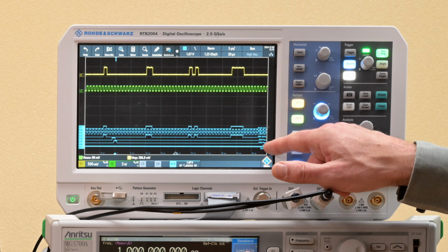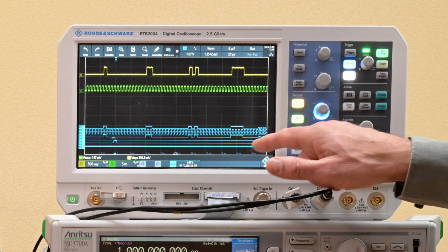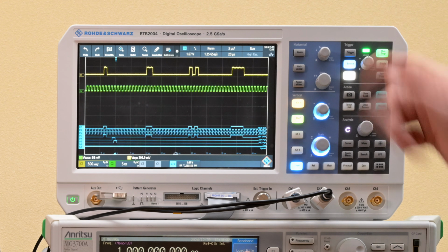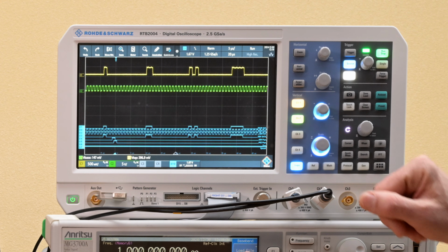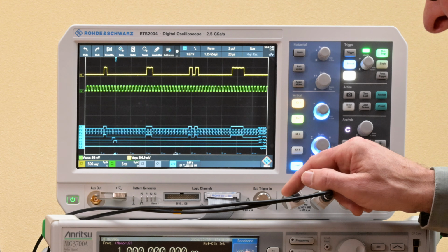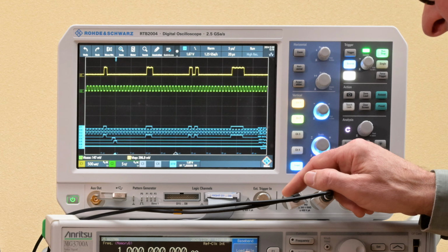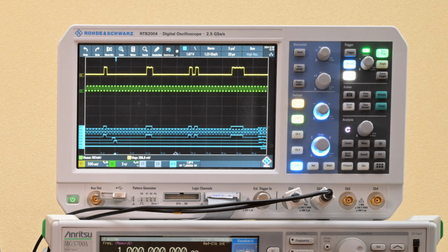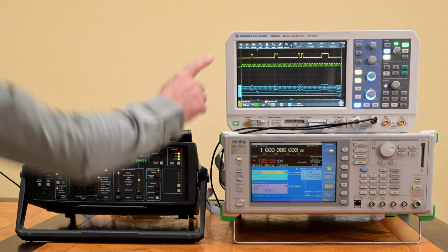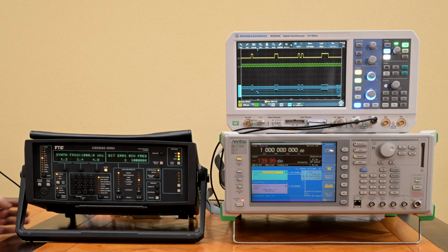And we also got an error signal, and when I just press the error button, we might or might not have seen an error coming by here, but then again we're sending over millions of bits, and the scope, because of blind time, will not show everything. But in a moment I will show you more of that. And we also got a signal here that the device is actually in sync status right here. So we basically see all the kind of important data coming in.